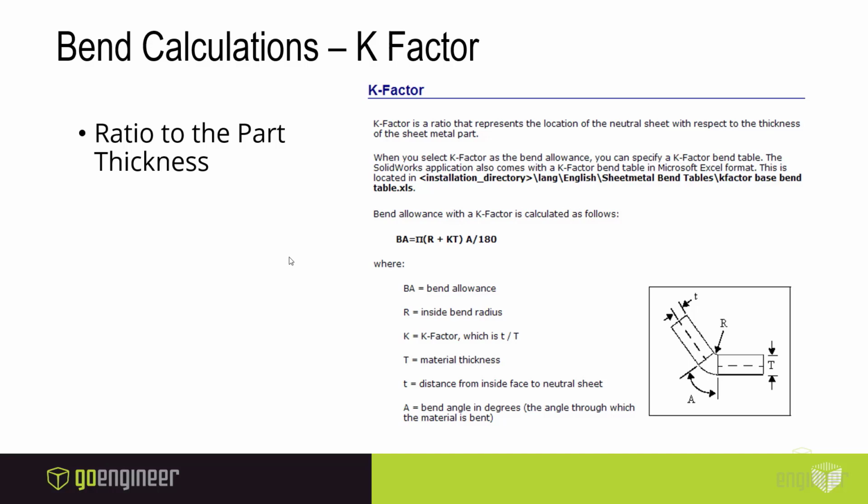So the K factor. This is generally a number that is put in as you create sheet metal, and it again determines whether the part is the same linear length flat as it would be folded, measured on the midplane, versus longer or shorter, again with tension and compression in each of those corners. Now, this is some voodoo here. The graphics that you're seeing here are just in the SOLIDWORKS help file, so you can find these particular graphics there.